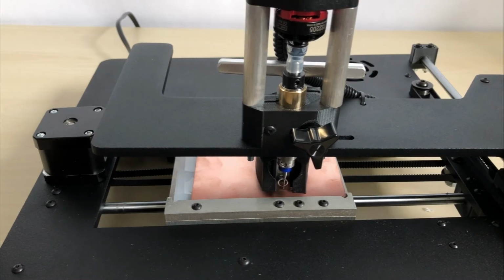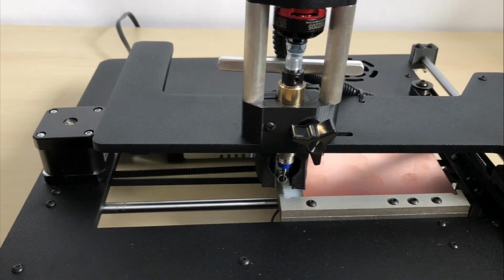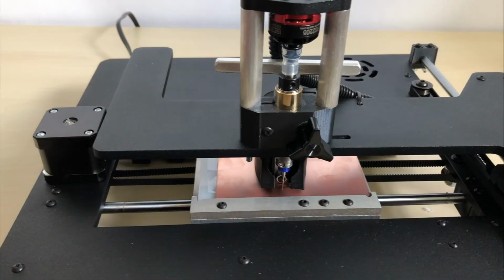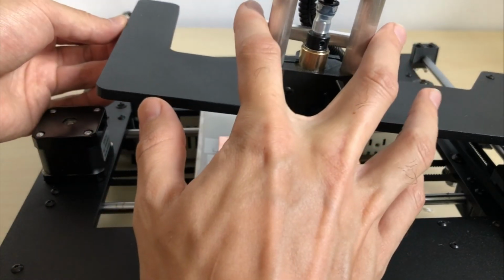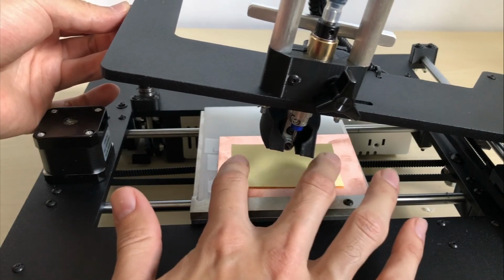You can also move the machine using the manual jog buttons in the control software, but make sure to lift the cutting bit off the copper surface before doing any XY moves, otherwise you will break the bit. The CuScribe has a height control bar that allows it to maintain a fixed cut depth for the duration of the print. For trace cutting, we want a very shallow cut depth. We will limit the cut depth to the thickness of a sheet of paper.